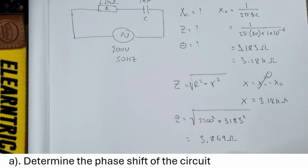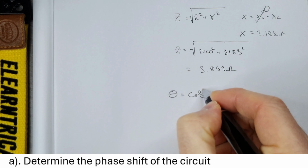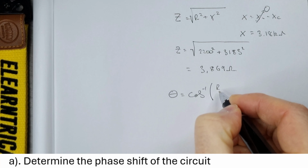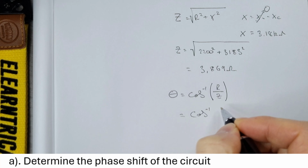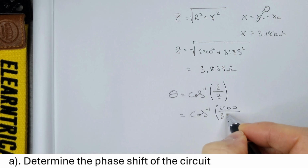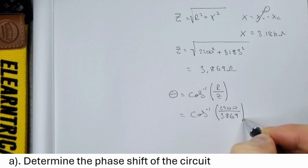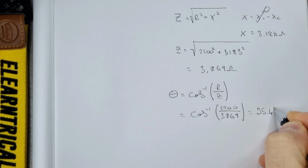and our total impedance for the circuit is 3,869 ohms. Our phase shift is the inverse cos of the resistance divided by the impedance, so cos inverse of 2,200 divided by 3,869 gives us a phase shift of 55.4 degrees.